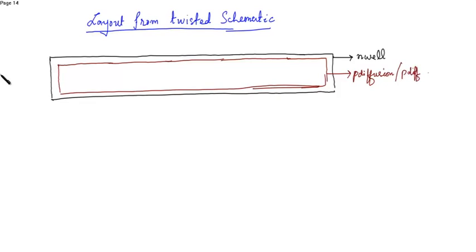Then you have the N diffusion layer. N diffusion layer is not taken in a single layer, because we need 3 NMOS and they do not have only the drains shorted. If you want you can even do that, but I'll take 3 NMOS.